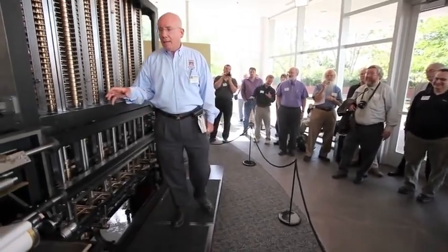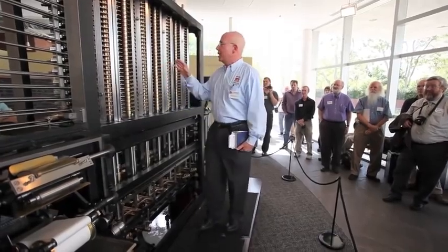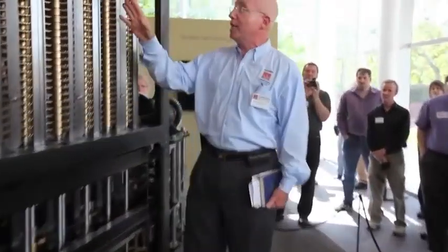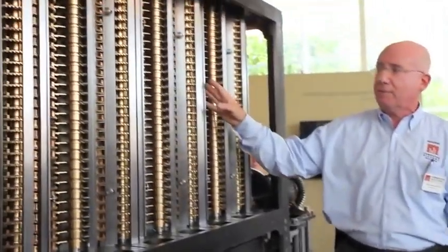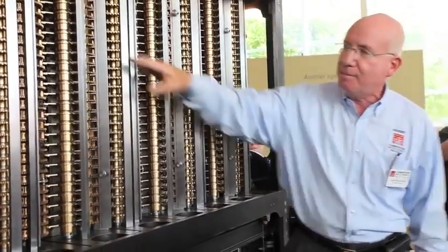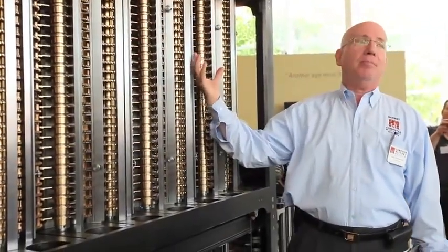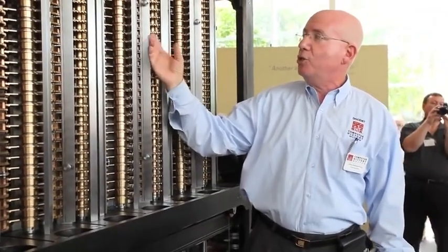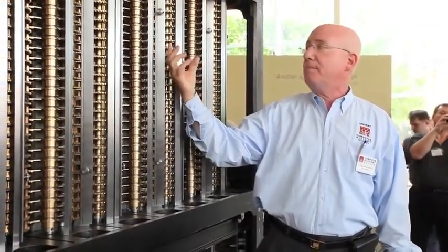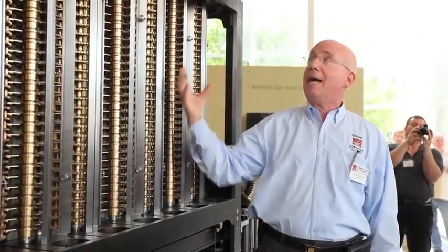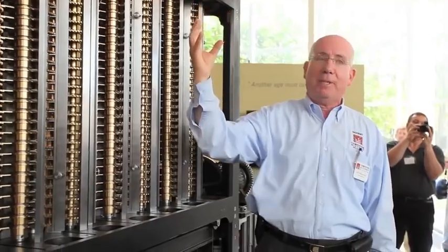So, okay, let's now look again. Let's crank it. I want you to watch as the addition takes place. We've got this equation set up, so in fact we're using 5 of the 7 difference columns. You will see the addition taking place by these big sector gears in between, adding the numbers from one column by rotating them back towards 0 value, transferring their value to the next column, and then resetting the column to its original value as it comes down. For that reason, these columns jump up and down.